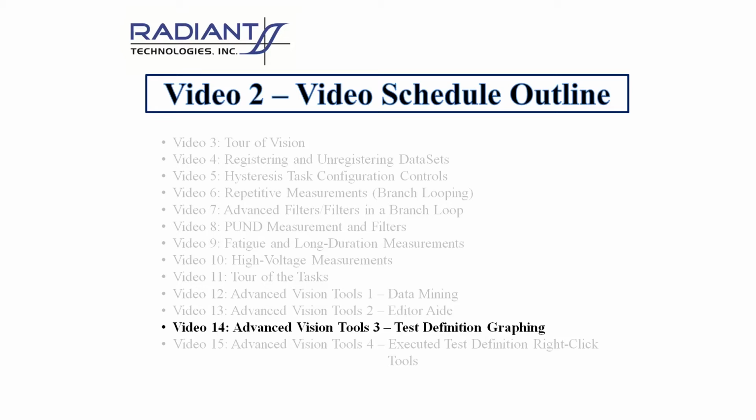In Video 14, I discuss a Vision tool that allows a test definition to be graphically represented to an audience. The tool can be used to display the editor test definition, or a dataset's current test definition, CTD, or any executed test definition. The graphical representation provides a type-keyed color and icon identifier for each task, along with details of task configuration. It also graphically represents dependencies between filter and branch tasks and their associated tasks. Text in the graphical tool can be edited for customization, and the tool can be copied as a Windows metafile for pasting into a Microsoft Office program or other target.